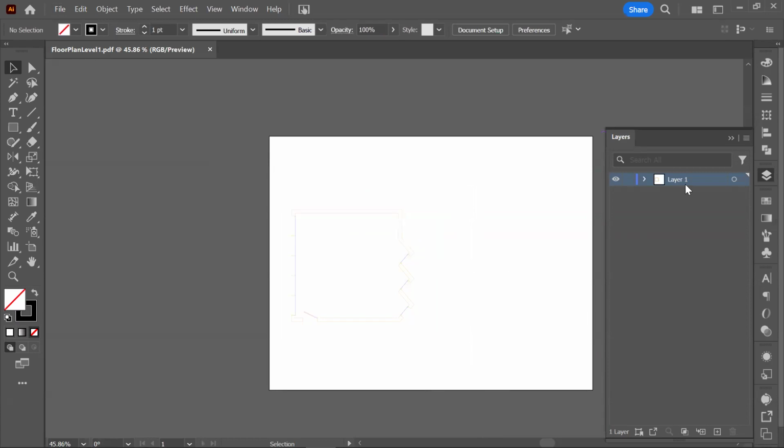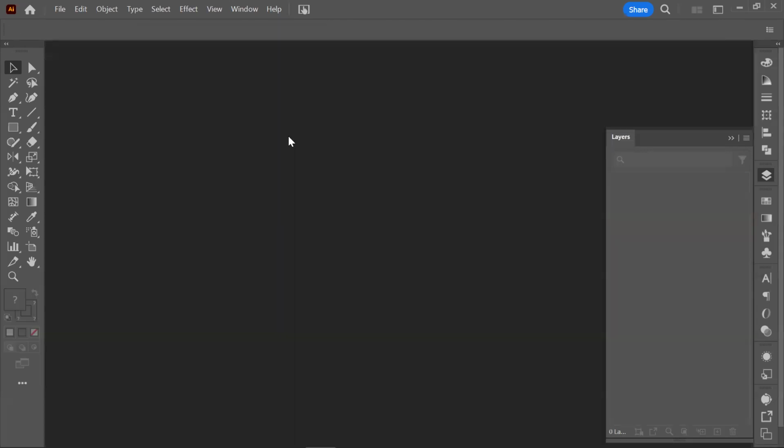Now, one thing to notice is that there's kind of a dummy set of layers. When you do a PDF, you lose those layers. So I'm going to go through another way, and this is a good technique if you clean up the line weights, which is the last thing I was going to talk about. You clean up the line weights in Rhino, which is not an option. You can bring it here to Illustrator, or use the PDF directly, you can print it. But I'll do that afterwards. So how do we actually bring in the number of layers so we can work with it in Illustrator more properly?